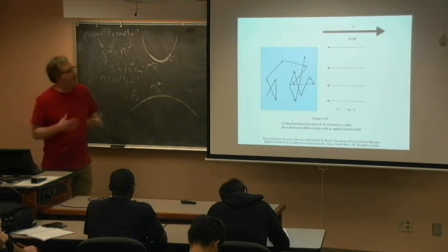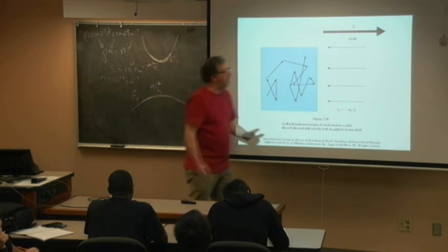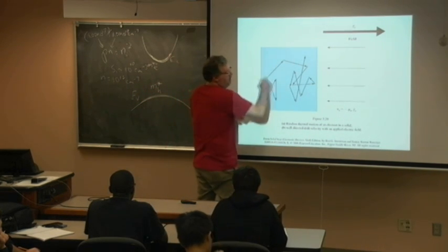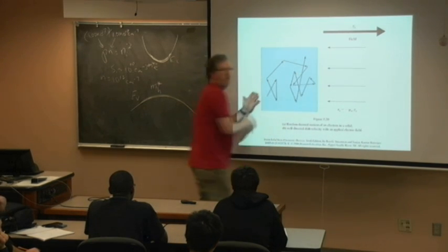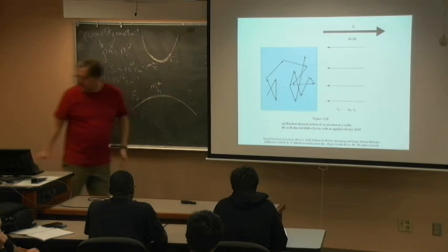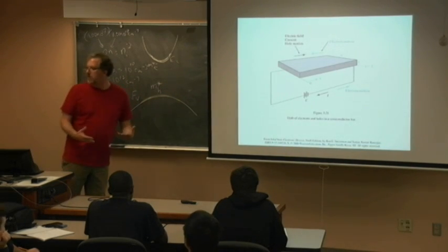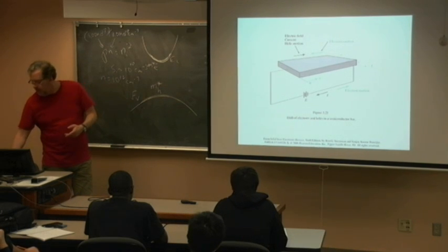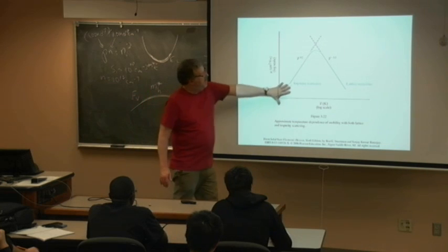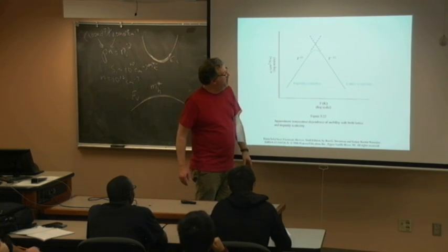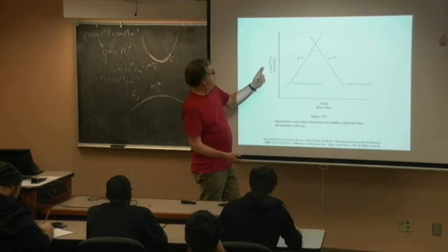And then the electrons are really not going in a straight line generally. They tend to scatter, and they just happen to be herded from one side to the other by the electric field. And yeah, so we can move them around. Oh yes, this was the lattice scattering. You probably can get some questions related on this. So we have two rate limiting steps that limit the mobility.